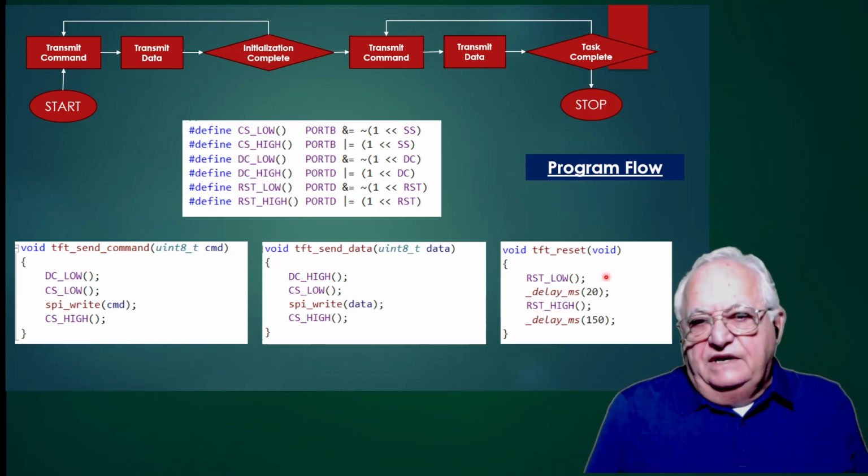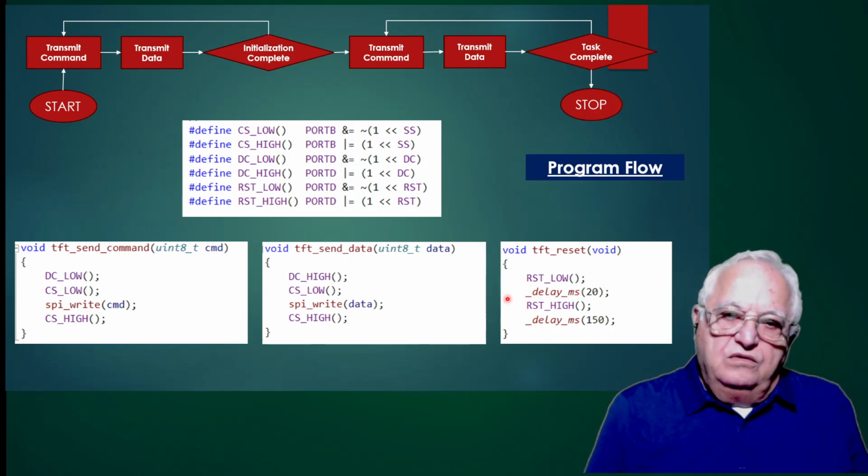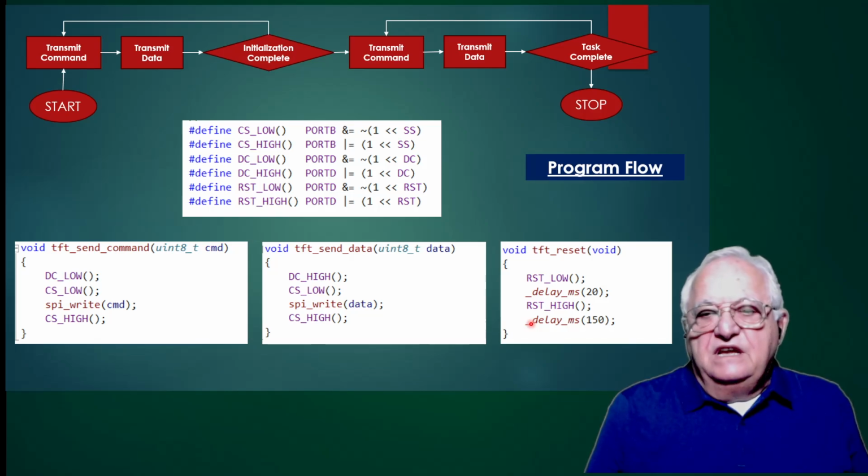Next, I have the TFT display reset. So I start, the display goes low, wait 20 milliseconds, display goes high, and then wait 150 milliseconds, and that's going to reset the display.